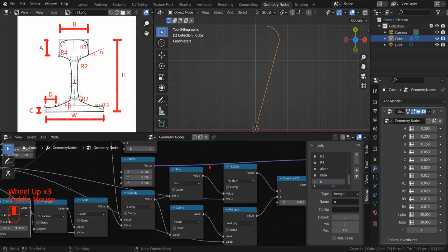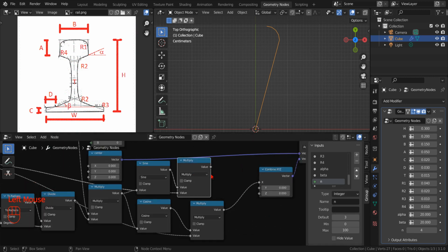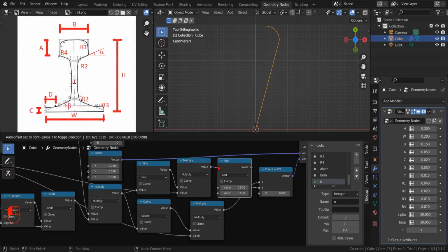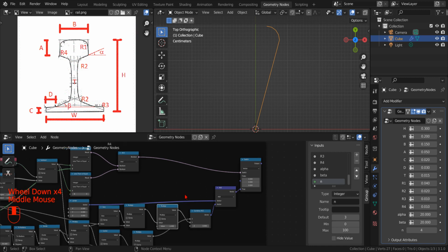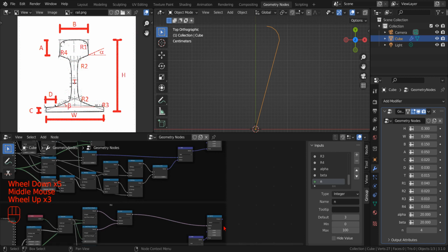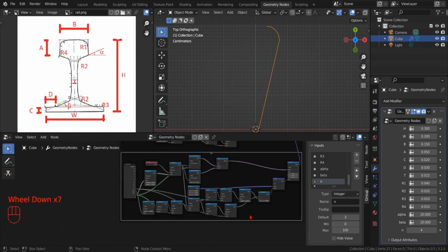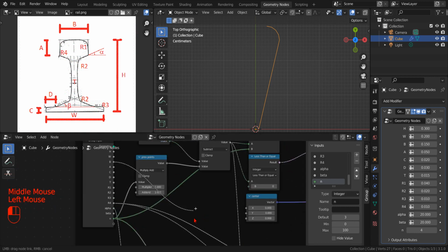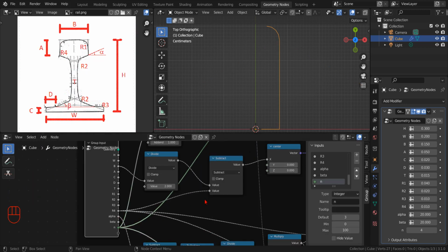Now we need to swap the x and the y component to account for the different orientation of the second corner, and we also need to add a new math node to change the sign of the y component by multiplying by -1. Now we can connect the output of this switch node to the false input of the previous switch node. In this way we can daisy chain the two nodes. Now we still need to define the center point of our rounded corner, so we use a new set of math nodes.